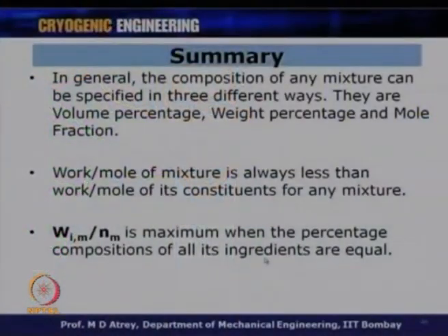So, in summary, in general, the composition of any mixture can be specified in three different ways. They are volumetric percentage, weight percentage and mole fractions. So, as you understood, what we ultimately want is mole fraction. Suppose the composition has not been given on a molar basis, we can convert the weight percentage into molar composition, while we know that the volume composition is nothing but the molar composition itself. So, in that case we do not have to do any extra algebraic calculations.